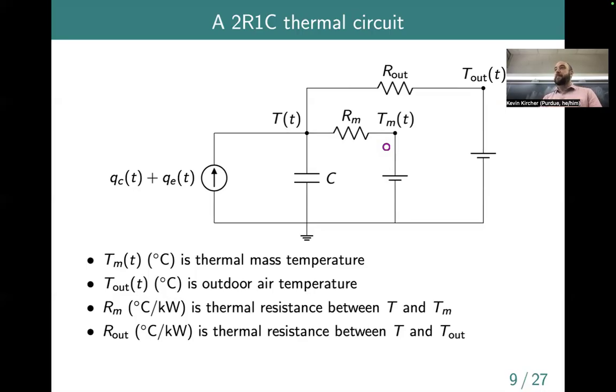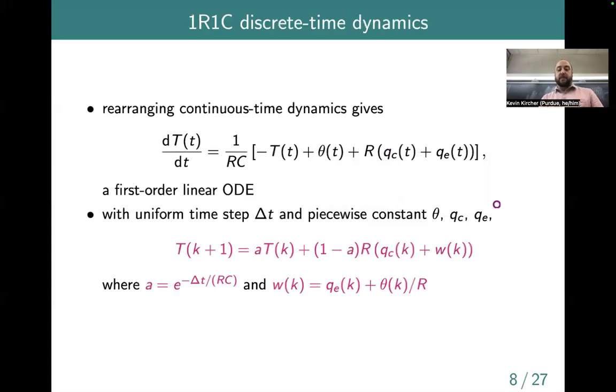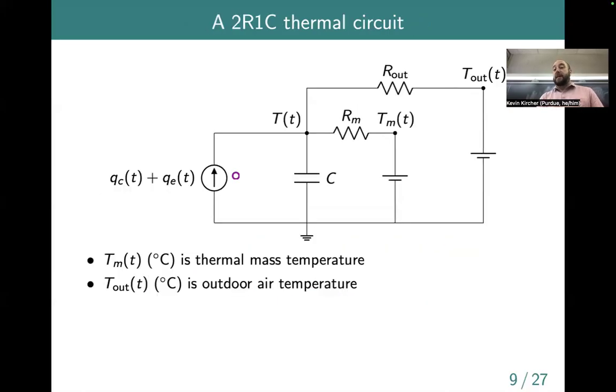If we look at it from right to left, does that make sense to do it that way? Yeah, so the question is, if we think of this as an electrical circuit, could we look at these things as sort of a low pass filter? And yeah, if you look at this differential equation, if you squint a little bit, this essentially ends up being the equation of a low pass filter. The time constant basically determines the cutoff frequency above which you're filtering out noise. So yeah, these things do have direct analogies to filters. They don't end up being super useful, at least in work that I've done previously, but if it helps you build intuition for what the dynamics look like, then yeah, for sure.